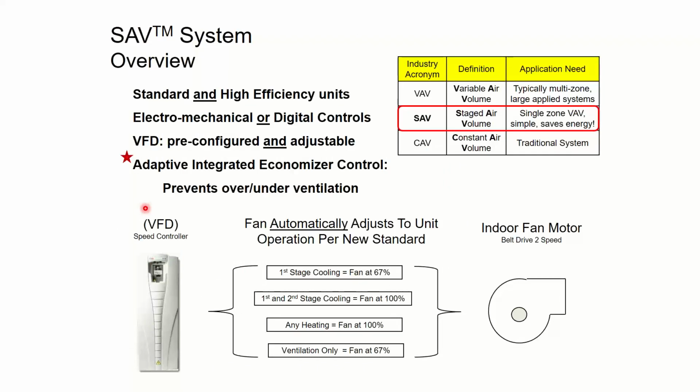Most state-of-the-art line systems from, yes, Ed. One quick, yeah, there's a question, sorry to interrupt you. Are advanced RTU controls standard on new equipment now? Great question. So are they standard on new equipment? Sometimes. So we'll go through what the code requires here in a minute, but if you are asking the question from Illinois and your unit is more than 5 tons in size, it's required by code and you have to do it.